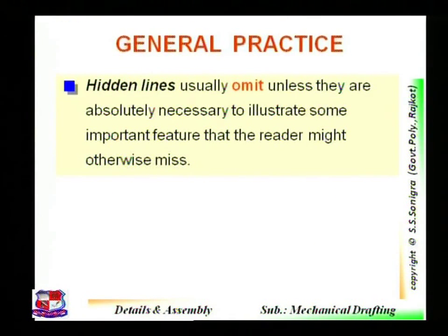In general practice, hidden lines are usually omitted unless they are absolutely necessary to illustrate some important feature that the reader might otherwise miss. So as far as possible, hidden lines are to be omitted, but can be used when it's necessary.